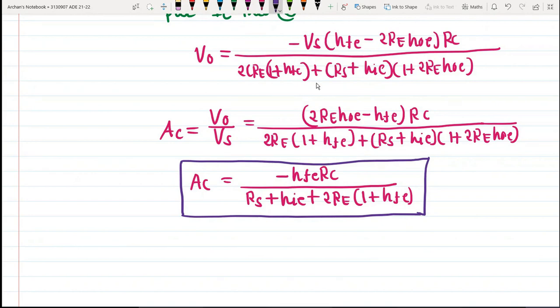Okay. And this common mode gain equation remains same whether our output is balanced or imbalanced. So irrespective of the configurations we are using, we will be able to get the same equation. Okay, it is not same in case of differential gain where we are getting two different equations of differential gain AD, but the common mode gain will be same for each and every configuration of the differential amplifier. Okay, so this is what we have got.